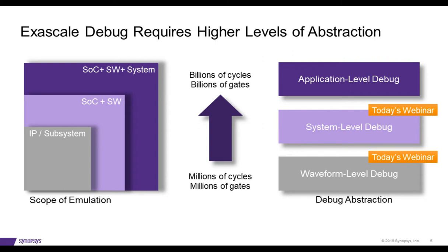Now, when we are trying to debug an issue on these different designs, for IP and subsystem we have predominantly done waveform-level debug. When you go to SoC level, running some software content, the premise I'm making is that we need to raise debug abstraction, and I'm calling this system-level debug, and we'll get to it in the webinar.